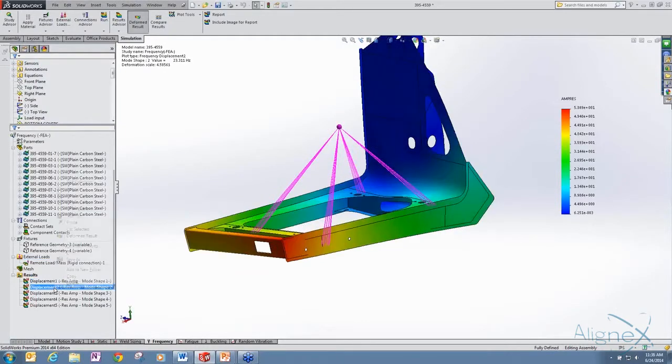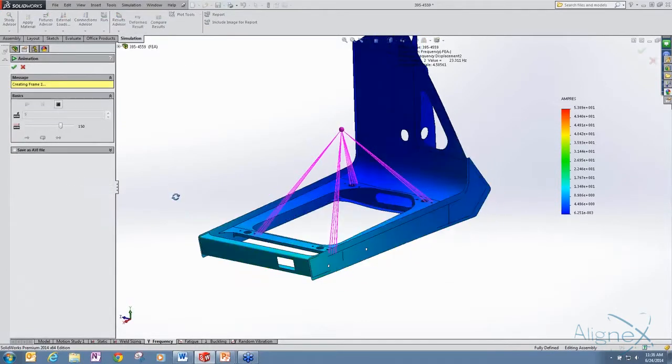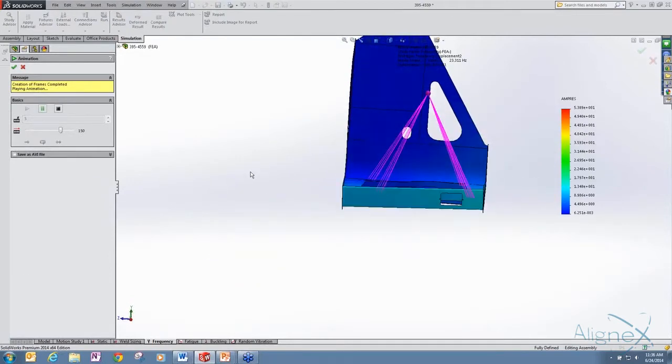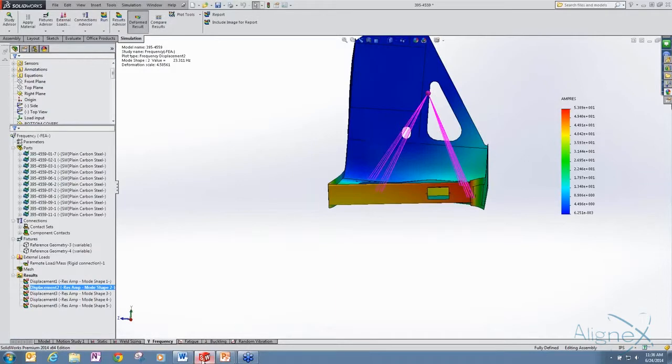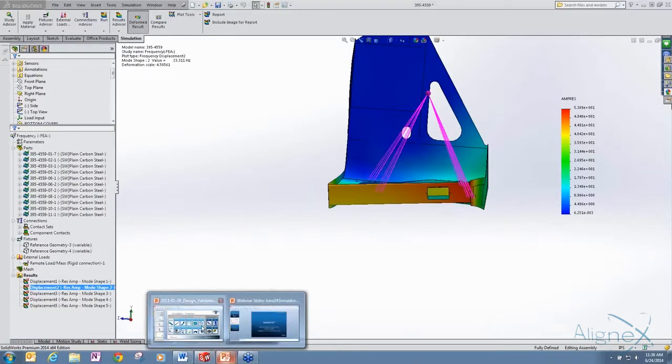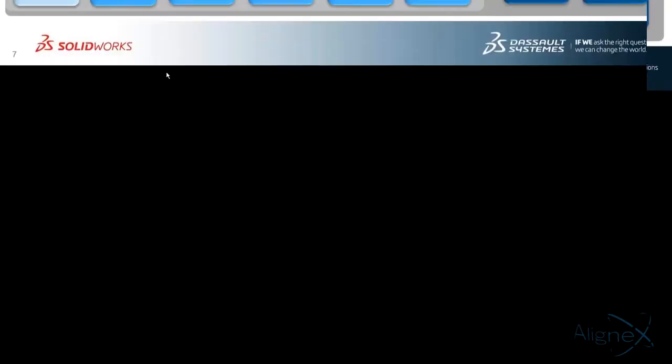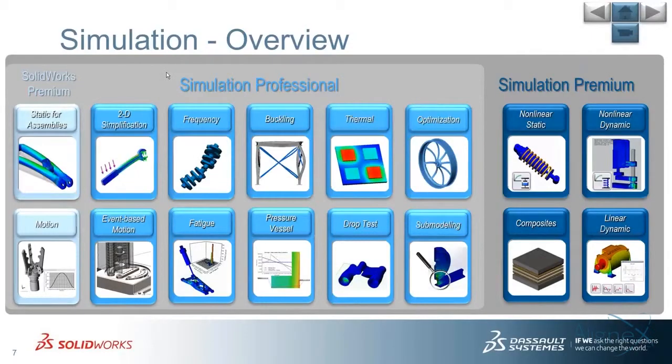Okay, so we can plot the different mode shapes. So the second natural frequency is more in the side to side and kind of twisting motion. So we can see what the mode shape will be at the second natural frequency as well. So we can actually plot those for each of the modes that we've solved for. So again, those types of studies allow us to investigate some additional modes of failure that would occur in deformable body mechanics.